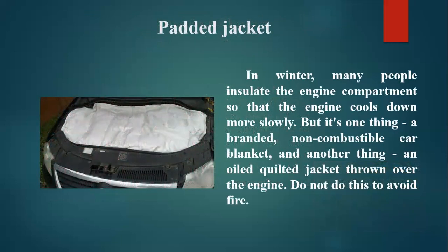Padded jacket. In winter, many people insulate the engine compartment so that the engine cools down more slowly. But it's one thing to use a branded, non-combustible car blanket, and another thing to throw an old quilted jacket over the engine. Do not do this, to avoid fire.